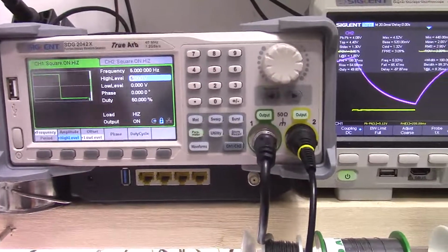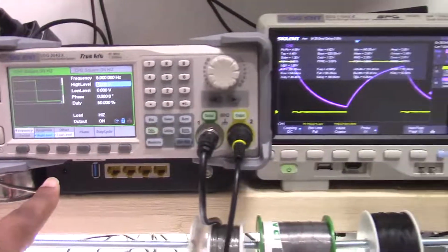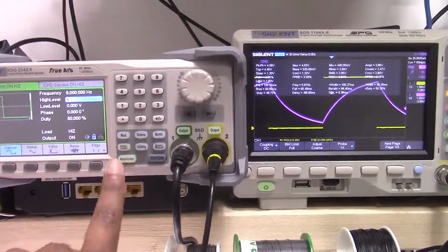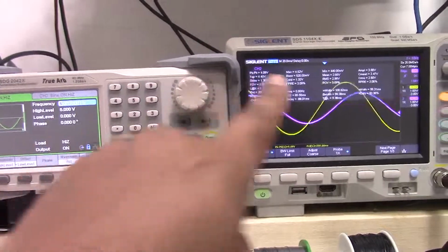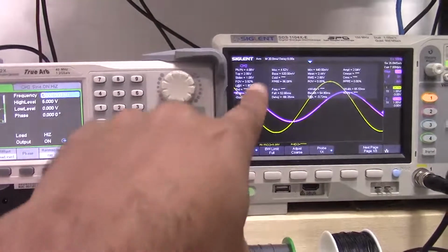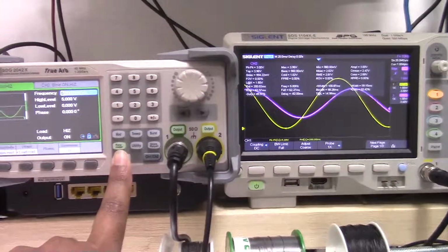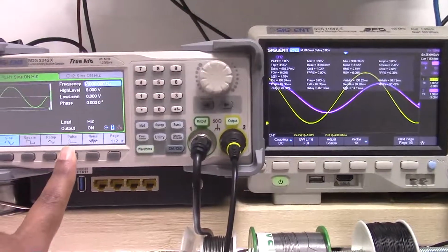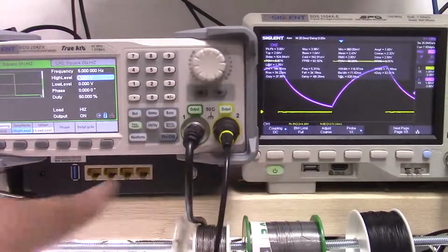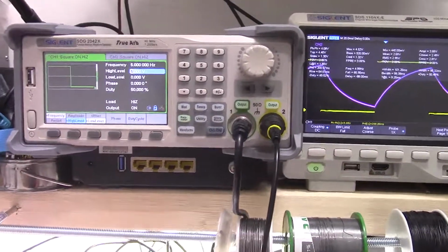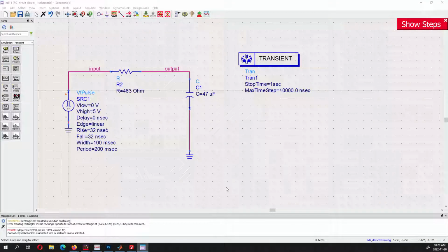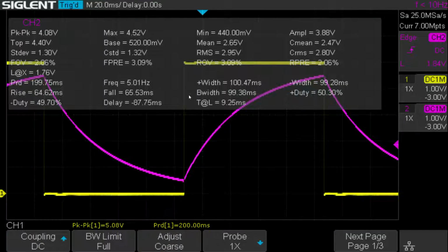This is the function generator generating the pulse width, and we can also generate a sine wave. If I go over here and generate the sine wave, it'll immediately show the sine wave. This is important for the Bode plot to understand the frequency response of this circuit. We're going to do both analyses right now. I'm going to go back to the square wave and then we'll analyze it from that perspective. So this is the circuit right now. This is the oscilloscope that I can show on my screen.